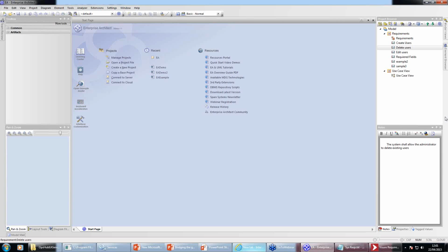Also by means of baselines, we can map a baseline to a release or a delivery. So everything contained in a given baseline is going to be in a delivery, and we can also use that for filtering the synchronization. For example, only those elements belonging to a certain baseline would be exported, so you can start modeling them. I would have loved to have more time to answer this, but take into account that tags are an option, and also baselines and so on.